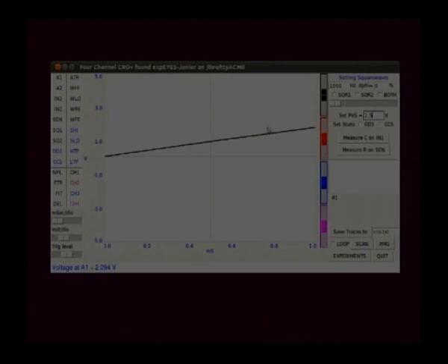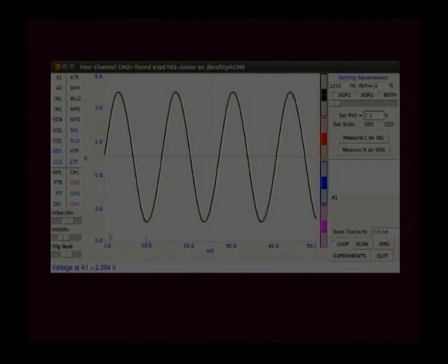Here it is already doing it, but let us change the time axis. This horizontal axis we can change, the milliseconds per division. Now, it is totally 1 millisecond. Using this slider we can change it. Now you can see I have made that total 50 milliseconds. Within 50 milliseconds you can see here around 4 cycles are there. So, this is how you can get complete information about AC.